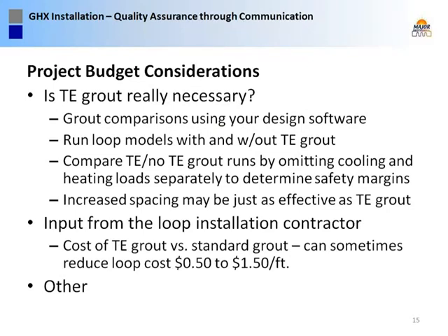So that kind of communication and feedback is really important, because you can use software such as GLD to test, do you even need thermally enhanced grout? And to test that, if I say I don't want a maximum entering water temperature more than 85 degrees, see if the load's cooling dominant, I'll take the heating load and run the loop model without it offsetting the heat load to see if a pure cooling heat rejection loop will handle it with or without the thermally enhanced grout.